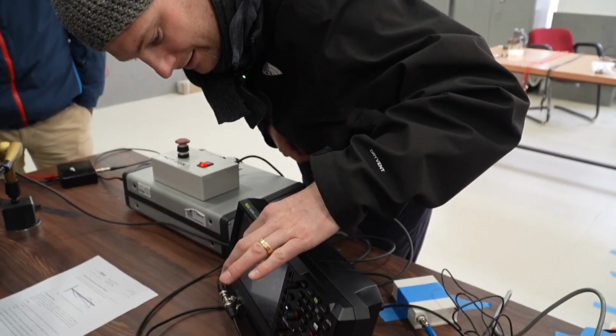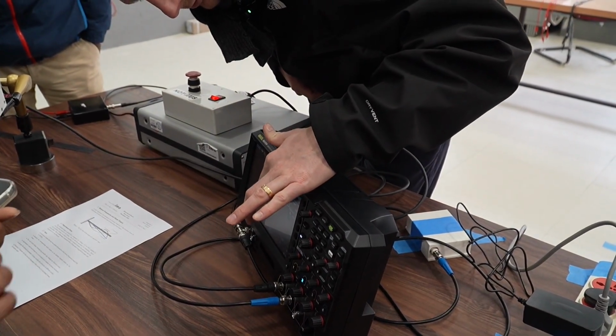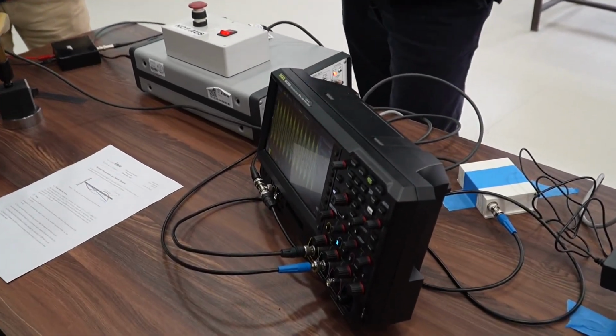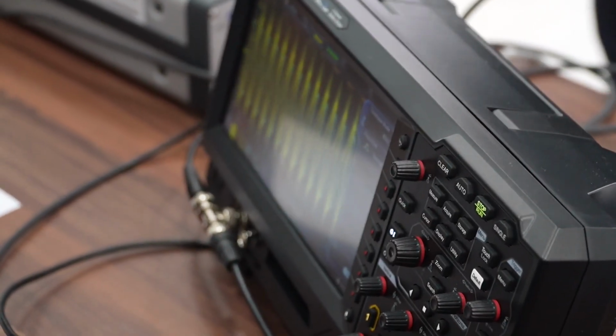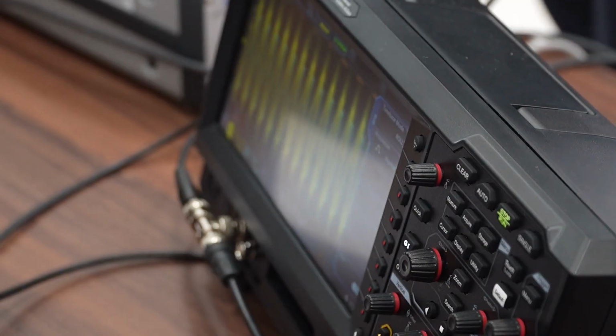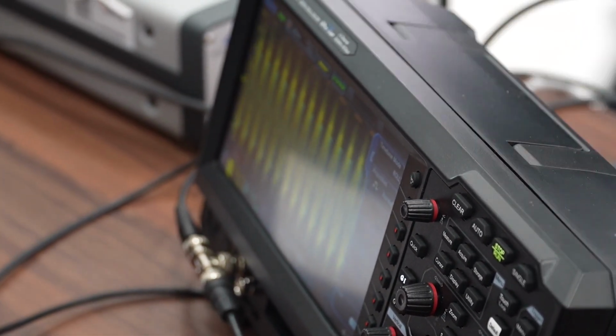Okay, so this is the first eigenfrequency, and now have a look for the second eigenfrequency. I suggest to go to acquire and to start in the time-based signal maybe again with the excitation. I also tell you right now, you probably have to look somewhere above 40 Hertz, otherwise we will search for a long time for the second eigenfrequency. So maybe start from 40, looking for the second eigenfrequency.